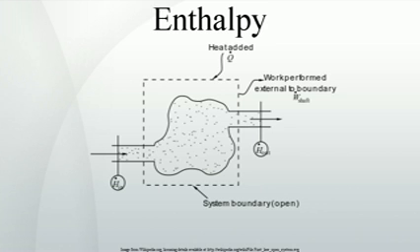In the first law for open systems, see above, applied to the system in Fig 3a, all terms are zero except the terms for the enthalpy flow. Hence, since the mass flow is constant, the specific enthalpies at the two sides of the flow resistance are the same. That is, the enthalpy per unit mass does not change during the throttling. The consequences of this relation can be demonstrated using Fig 2.